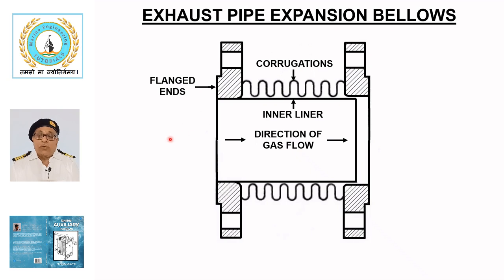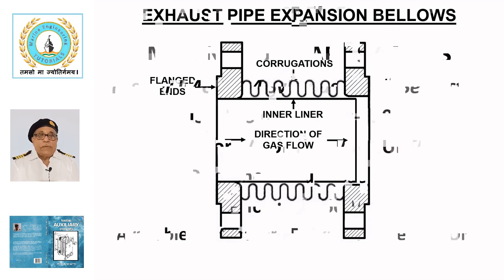When installing bellows, the only critical requirement is ensuring the correct direction of gas flow. Otherwise, the bellows may crack and cause gas leakage. Bellows should be routinely inspected for early signs of failures. This completes our study of steam traps and pipe expansion arrangements.